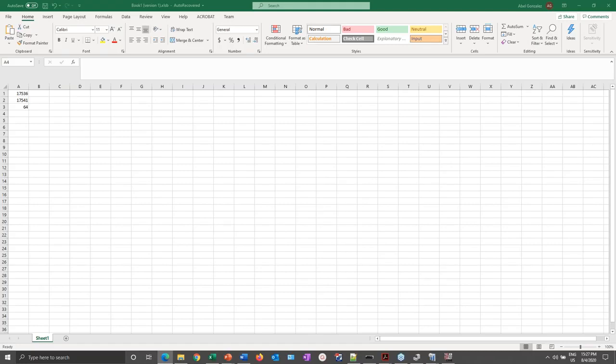Then you might have what I've seen as storm settings, so if you have a storm or some weather coming into the area and you want to switch to an alternative setting group, you can test both groups. The thing is that when you read the settings from the relay, it's going to tell you whatever that active group is at that point in time. That will technically be your relay settings that you will test on.